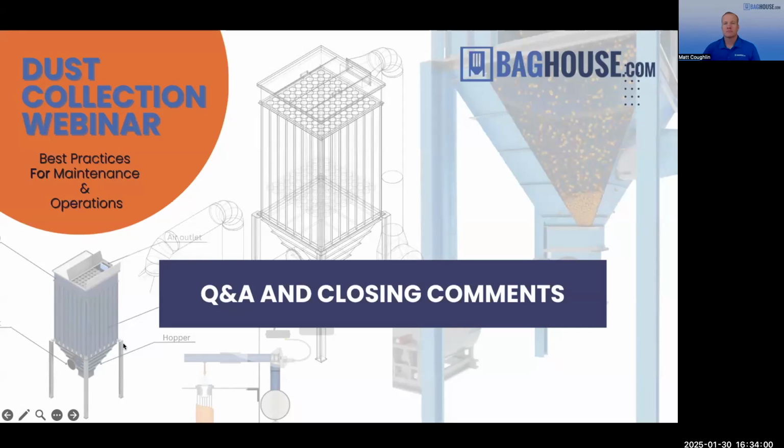Yeah. Kind of along those lines, we had some questions that came in about how to identify damaged bags. A lot of people wrote in saying, when we have a leak, it takes a lot of time to go find the leaking bag. How do I find a leaking bag in the midst of hundreds or thousands of filters? What would you say? So the easiest way is to do a dye leak test.